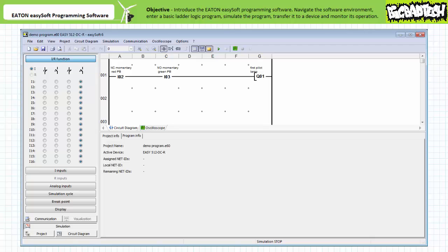A momentary contact is symbolized with a straight bar on the operator, whereas a maintain contact is symbolized with angled bars on the operator. I know in the comments section I've indicated the devices attached to inputs I2 and I3 are momentary in nature. However, let's instantiate them as maintained contact devices for the purposes of this simulation, since it's easier for me to get a screen capture of the running simulation without having to keep one hand continually on the mouse. Here we've instantiated the simulated field input device attached to input I2 as a normally closed maintain contact button, and the simulated field input device attached to input I3 as a normally open maintain contact button.